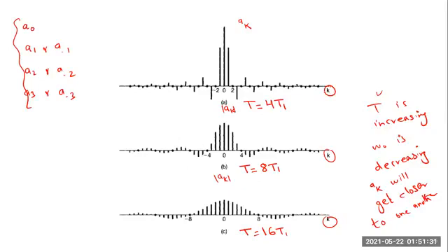And the point is, if you remember, k is a discrete number, so it is 0. Of course, this is the same for all cases. The DC component is the same for all. In this case, this 1 corresponds to omega naught. In this case as well, this 1 corresponds to omega naught. But now, because omega naught is decreasing, even though it corresponds to omega naught, it is now closer. It is getting closer to this DC component. So the difference that you can see in the plot of the Fourier coefficients is because the period of the signal is changing.